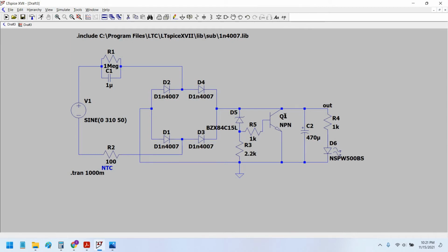And as soon as the voltage shunts to 0, the Zener would stop working, and hence the transistor would again become open, and this loop will continue until the voltage at the output becomes stable, DC stable, equal to the Zener voltage of this Zener diode.